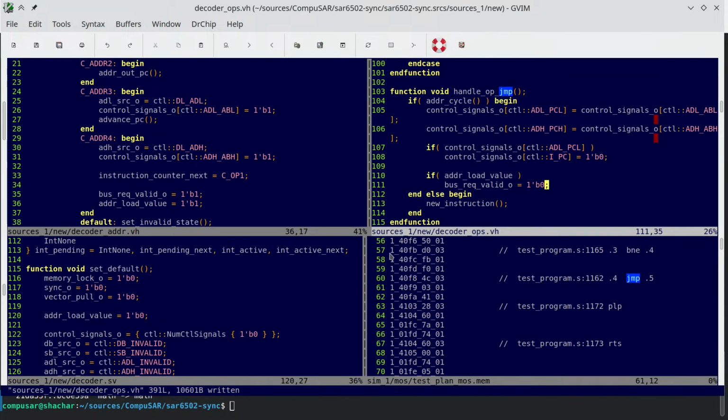It's not Lua, it's System Verilog. It's an HDL, hardware description language. It looks like software, but it isn't. Essentially, the synthesizer sort of squashes, inlines everything, squashes all the different code paths, and then takes the last assignment under each situation.